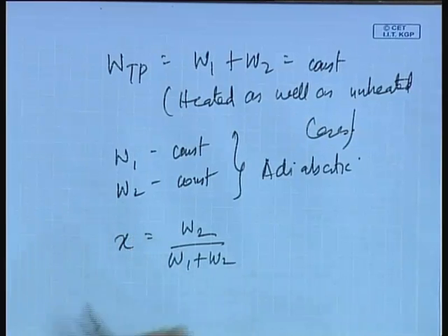But remember one thing, alpha is not a measurable quantity, but X is definitely a measurable quantity. It can be measured from heat transfer or heat balance equations or enthalpy balance equations. In the last class we had already mentioned that if we know the heat flux, if we know the amount of subcooling of the inlet liquid, we can find out X. In other words, if both the liquid and the vapor are in equilibrium, under that circumstance also we can find out X. So, X is definitely not a non-measurable parameter, it is a measurable quantity, or it can be derived from measurable quantities, unlike alpha.